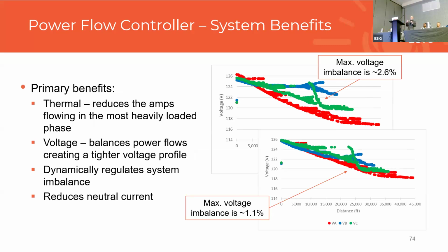Okay. So now we know how we're modeling it. What are the system benefits? And this really gets back to what was just previously discussed. Typically, what we see is thermal or voltage constraints when we're thinking about hosting capacity. There are others, but those are pretty large primary ones. When we look at hosting capacity maps, that is very common on what everything is being based upon.